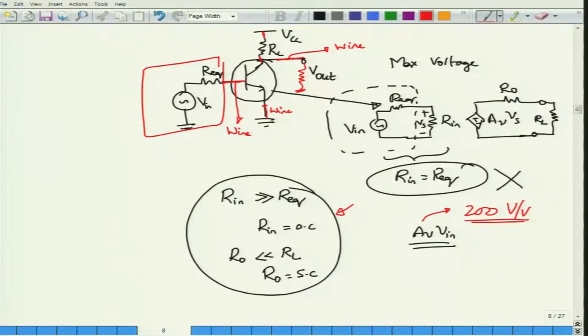But unfortunately, when you go to high frequencies, all these lines which I drew and then happily called wires are no longer wires, they are all transmission lines. Okay. You see this thick line that I am using to indicate that these are all transmission lines. So, what is the property of a transmission line? You might think that you have connected a certain load here of some RL value, but unfortunately what you have connected to the collector terminal is not really a wire but a transmission line.